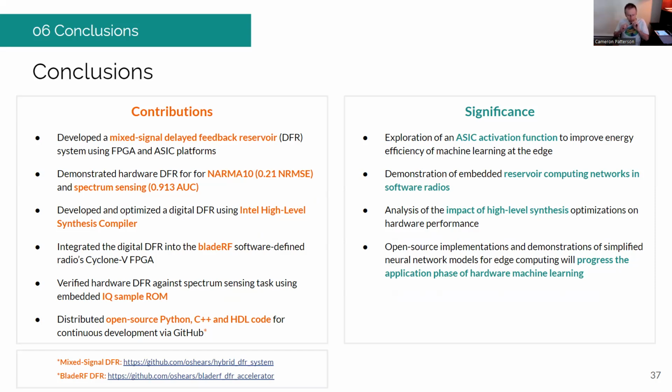You're using high-level synthesis, that's state of the art. However, I have used both Intel and Xilinx high-level synthesis tools in past projects. This was some time ago, but I found the Intel tools to be not able to produce as good results. Perhaps that's changed. In fact, in your discussion, you point out in terms of resource usage, it's primarily due to various floating point operations like the power function.